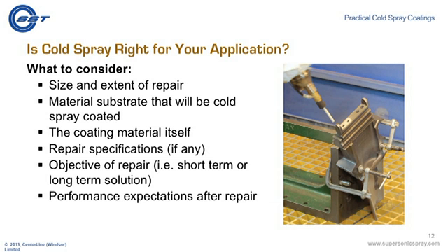As an example, we can repair a lot of magnesium components using aluminum, or we can repair cast iron blocks using nickel-based coatings. What is the objective of your repair? What are you trying to accomplish here? Obviously, you want to salvage a component to its original specification, and you want to maximize the resale value or usable value within your operation.